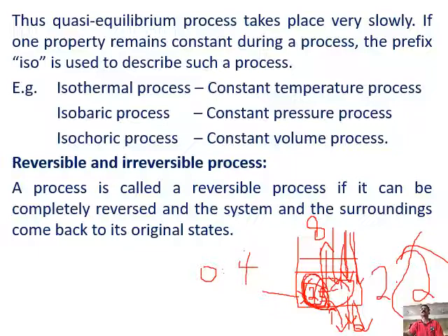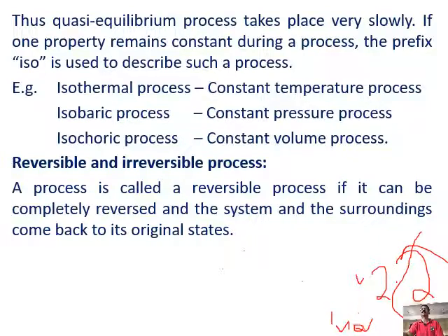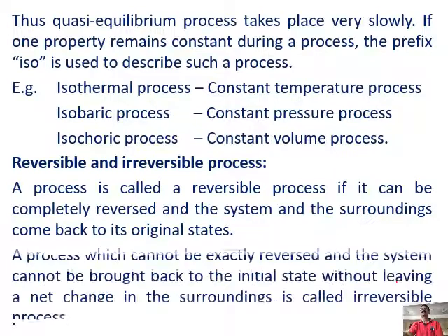But suppose you compress this further to remove this 0.4 kilojoules, then you need extra work. That means the surroundings will not come to their initial state. So this is not a reversible process. The second example I gave is for an irreversible process, meaning either the system or the surroundings doesn't come back to its initial state.